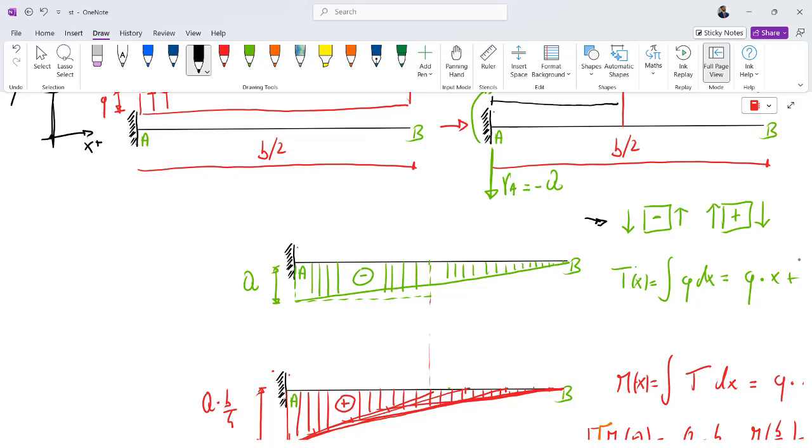In this case, when the force acting on the X portion of the beam is directed from up to bottom, and the force acting on the left of this dx, this elemental portion of the beam, is acting from bottom to up, we have a negative shear. Instead, in the opposite convention the arrows are inverted.